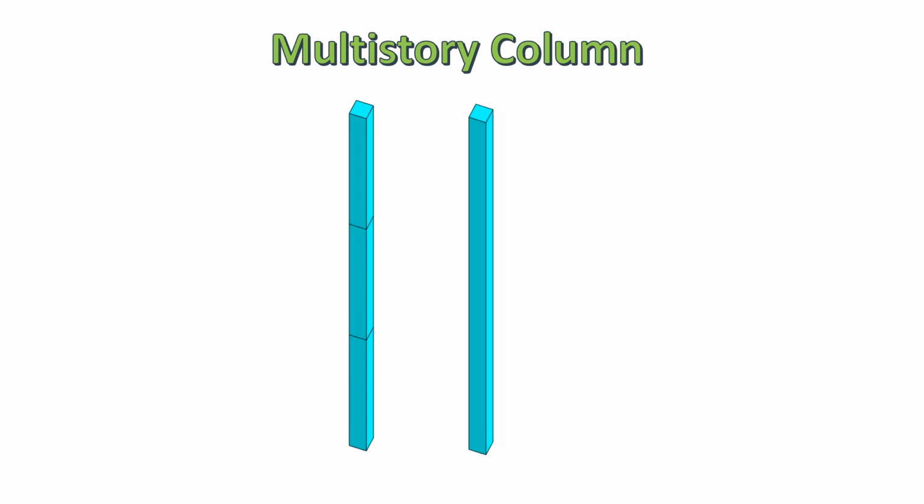For the multi-story column, the structural column model could be either non-splitted or splitted. For me, as the structural designer, since the column could be changed a lot during the design phase, such as constant relocation, resizing, and level changing, it is much more convenient and saves a lot of time with the non-splitted column. The structural analysis software such as ETABS will automatically split columns at every single floor level during the transition from Revit to ETABS.